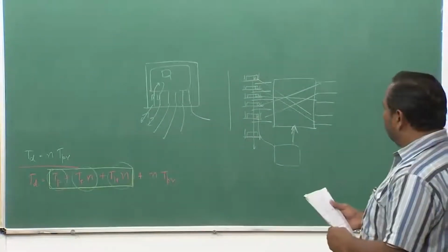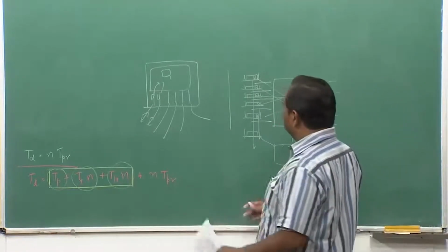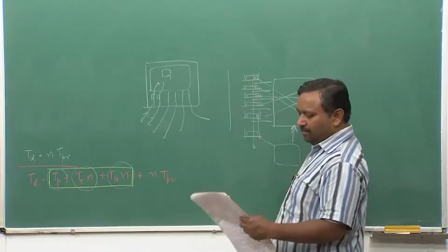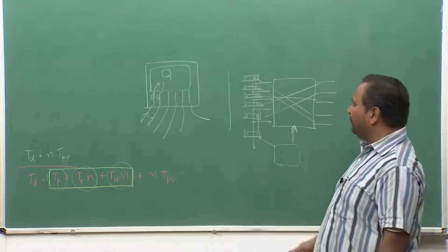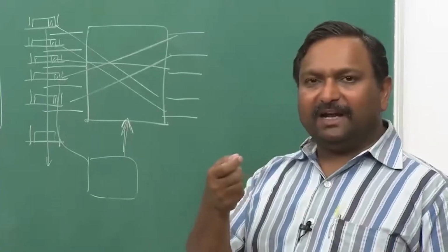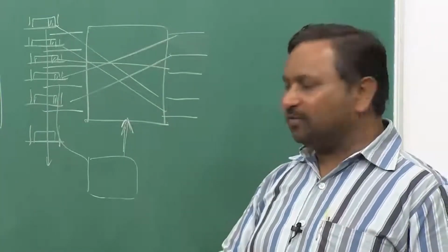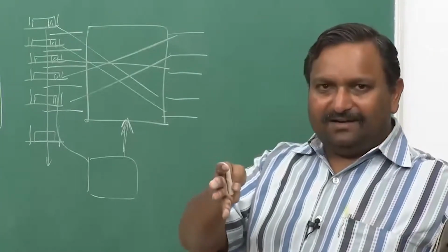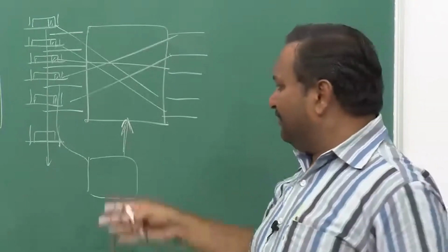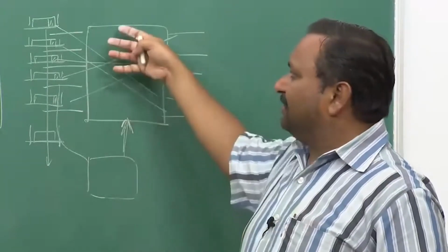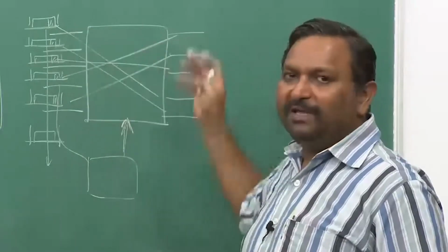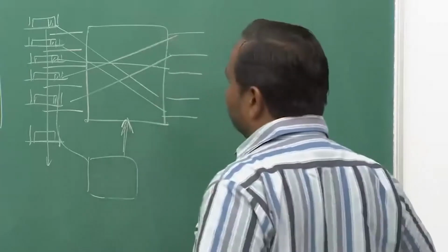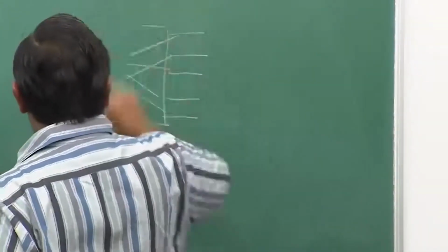So now typically what will happen is, there has to be an interface board on the crossbar, so that when the packet comes in, the header has to be tapped, and made available to the processor. The packet has to be held there, so that there is sufficient time in which the processing is done, the cross connection is set up, and only then should the packet be pushed into the switch. So we will actually be having an interface board here.